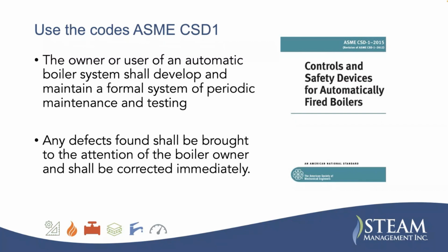ASME CSD1 is in about 40 different states. It's a great code. And I tell this to all the mechanical contractors or service contractors here: if your state adheres to this, you should get a copy of the code and give it to every one of your service technicians, because ASME code CSD1 handles boilers up to 12,500,000 BTUs.